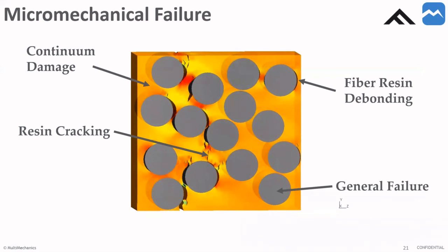So in the example of this specific material, the fibers that Fortify is using and the resin they're using, we can take some standardized tests, whether that's 45-degree, 0-degree, or 90-degree alignment. We run that data through the optimizer, and it automatically runs hundreds of simulations, tweaking this parameter, converging on an optimal cohesive zone parameter.